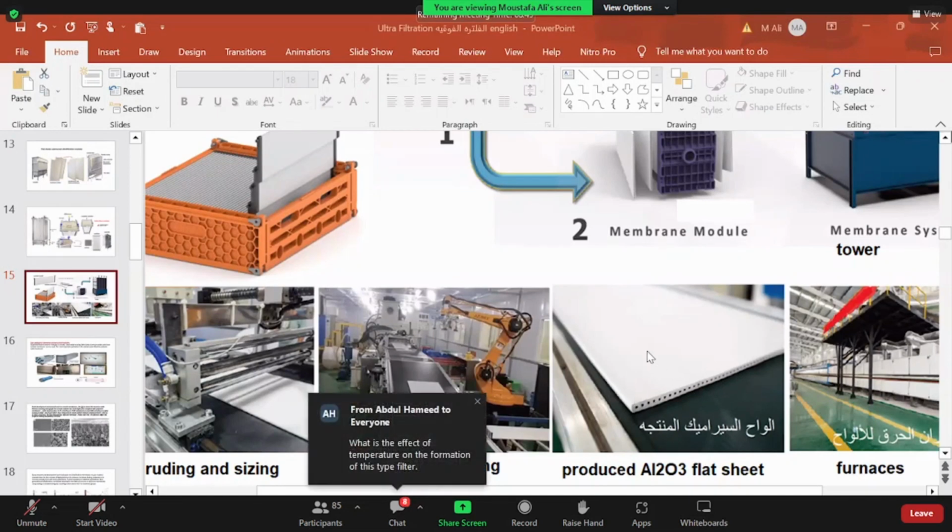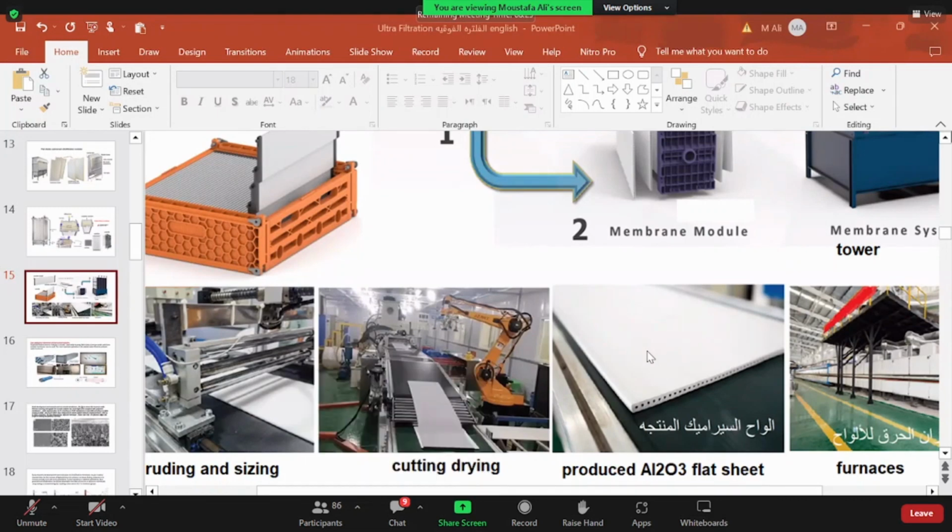So we manufacture the silicon carbide membrane inside a closed furnace, vacuumed, filled with argon at a very high temperature, 1850 degrees. The refractories inside it are around 10 to 20 centimeters thick. I saw it in some furnaces already, made from graphite. From graphite, it can take temperatures over 2000 degrees. So this is simply the production process.